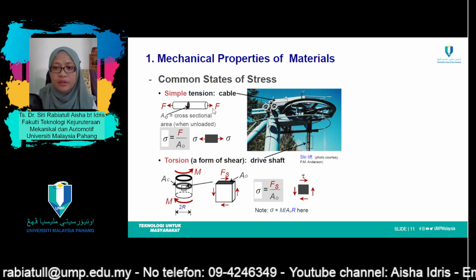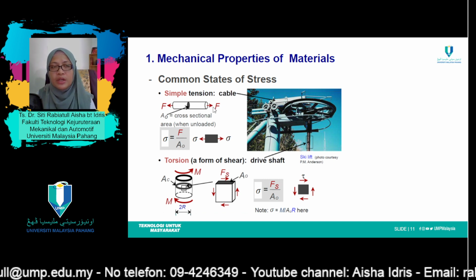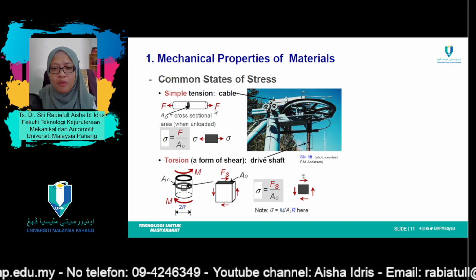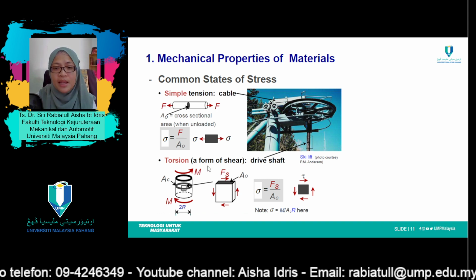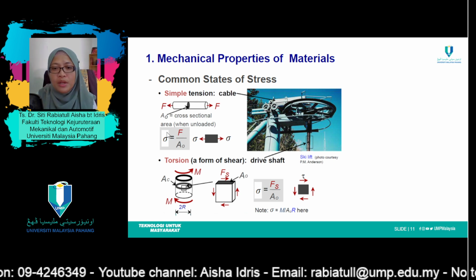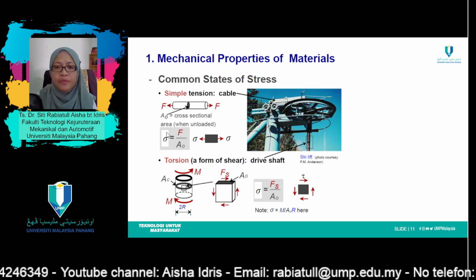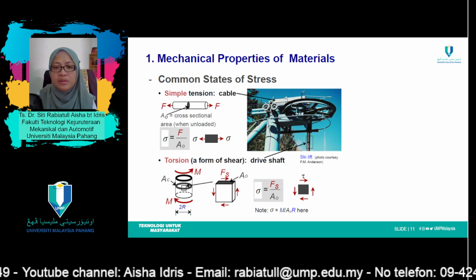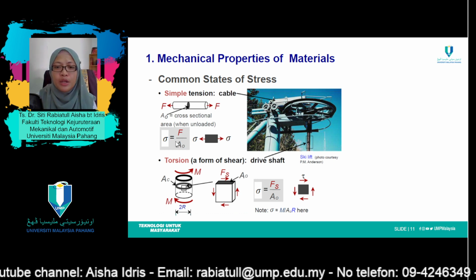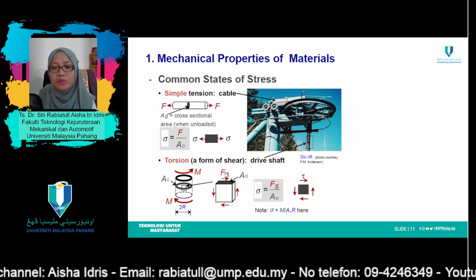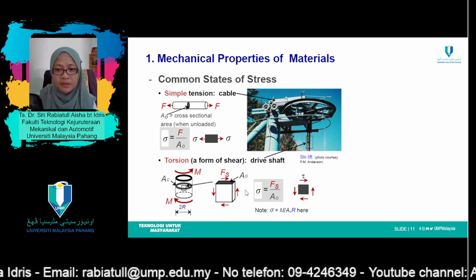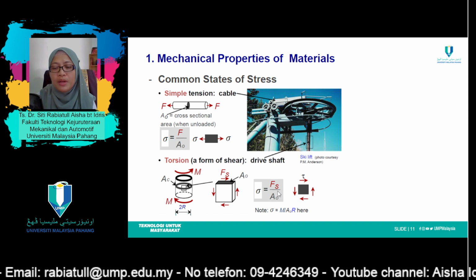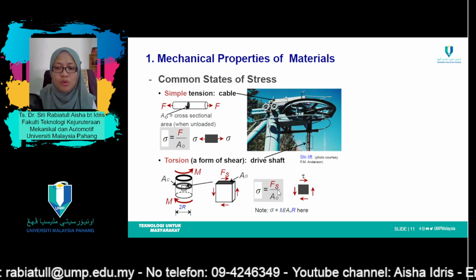it's either directional, unidirectional forces or torsion, which is acting on this shaft in this case. And the formula to calculate the value of stresses or nominal stresses for a cable equals F over A. And for torsion, in this case, shear stress exists on that structure. And the formula is the same, force over area.